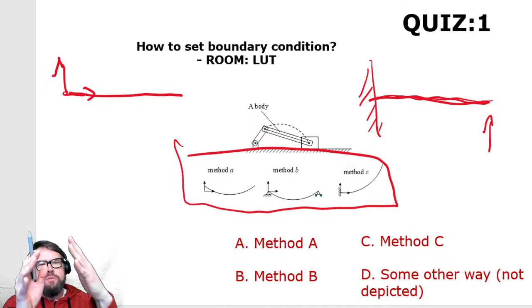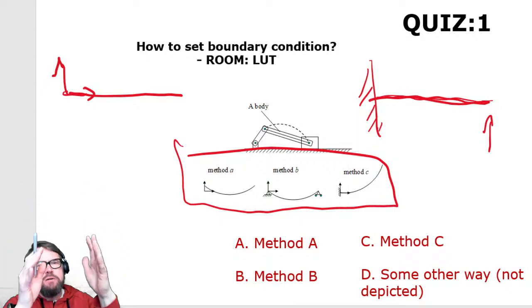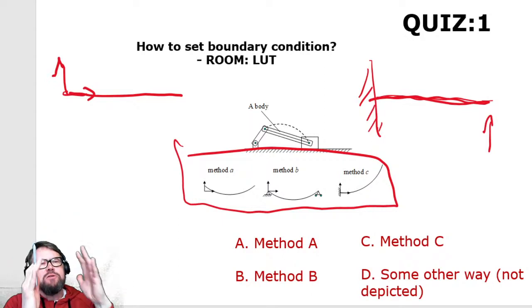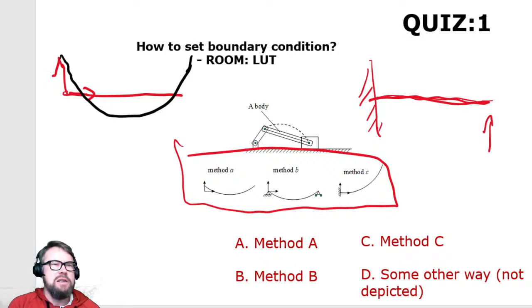All right, so first there will be rigid body modes, so the structure will move left, and up and down; those will be rigid body modes. It can have a rotation as well. But the first deformation mode will look something like this. I'm going to change the color here. The color will be black. So the first deformation mode will be something like this. This is like a banana mode.